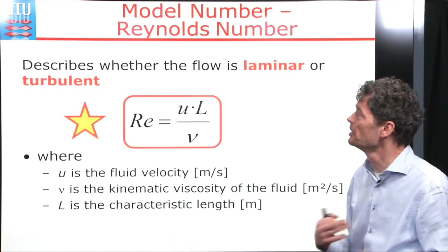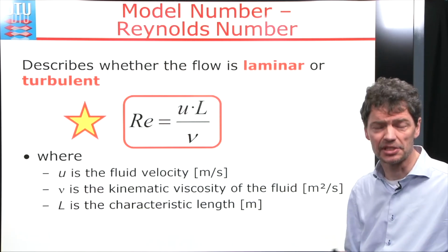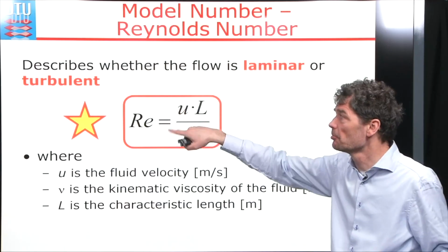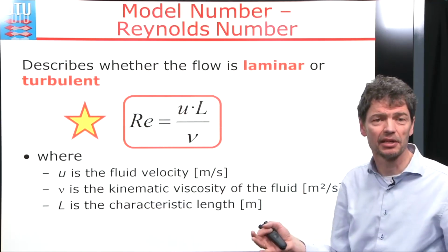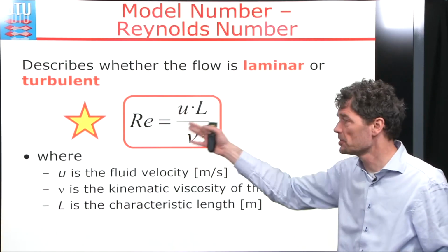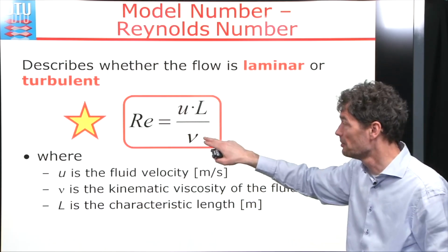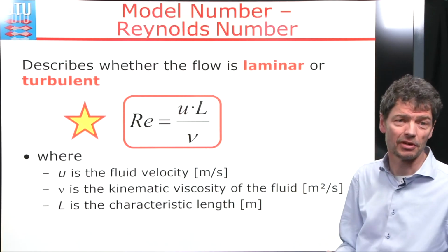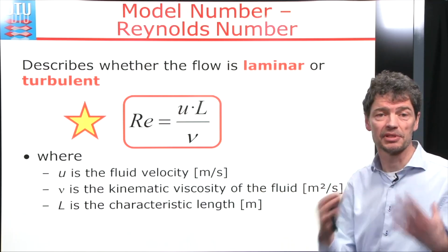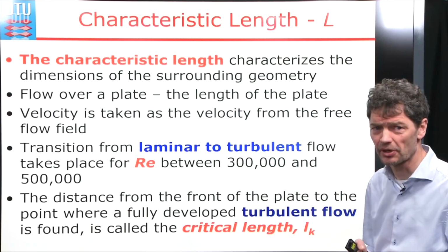So to calculate the flow, we are also interested in the flow velocity, and there you can use the velocity in meters per second. But as is characteristic here, because we want to generalize things as much as possible, we characterize the velocity with a dimensionless number, which is the Reynolds number. So again, it's the velocity, but we multiply with a characteristic length, and we divide by the kinematic viscosity of our fluid, and thereby, with the units, if you check those, the Reynolds number becomes dimensionless. There's no unit to it. So it can be, you could say, general for us here.